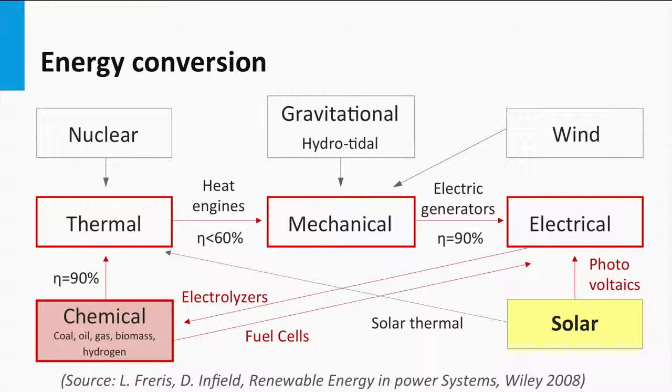This is what we call solar thermal energy. Examples are heating of water flowing through a black absorber material that is heated in the sunlight. This heat can be converted into electricity again using heat engines. As the conversion efficiency of heat engines strongly depends on temperature, concentrated solar power systems are used to generate electricity through solar heating using so-called high-temperature collectors.